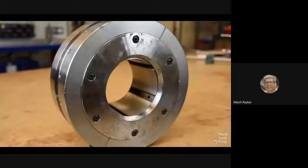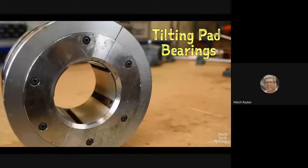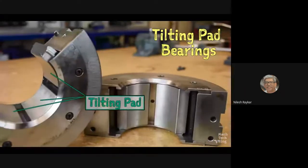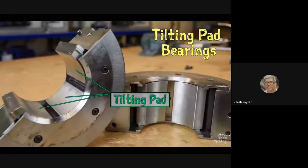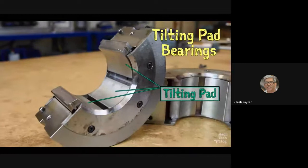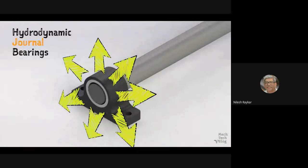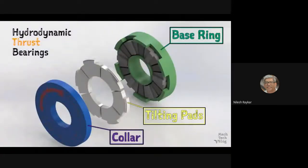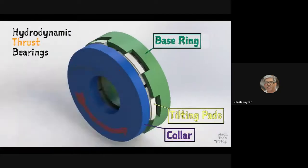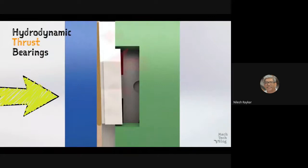Some bearings are designed with tilting pads equally spaced around the inside of the bearing. The pads can pivot slightly, and each one forms its own hydrodynamic wedge. This helps to stabilize the shaft. Now, normally hydrodynamic bearings can only handle radial loads and are free to float axially. But when the tilting pad design is applied to the face of a bearing and mated to a collar on the shaft, then axial or thrust loads can also be supported.